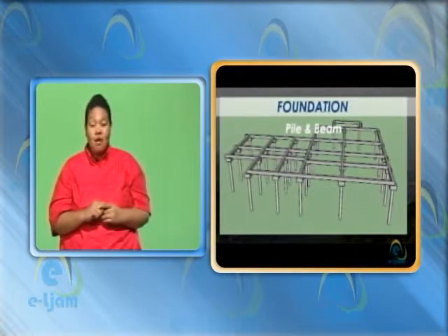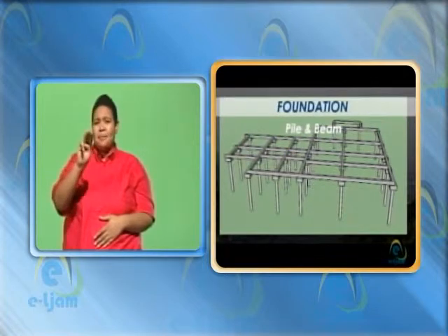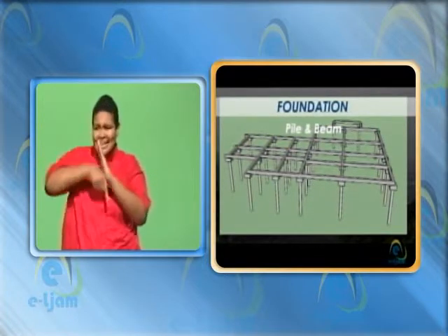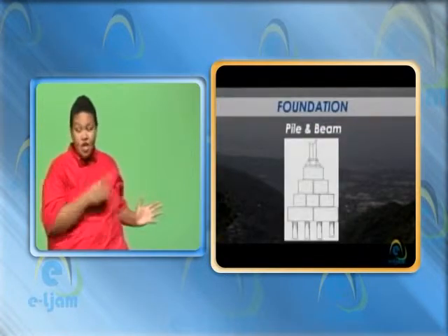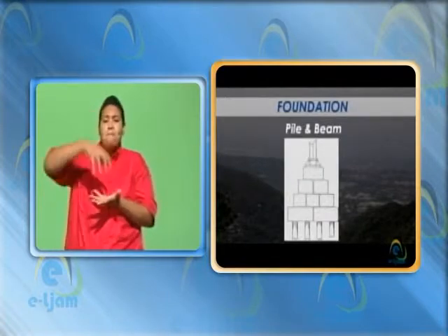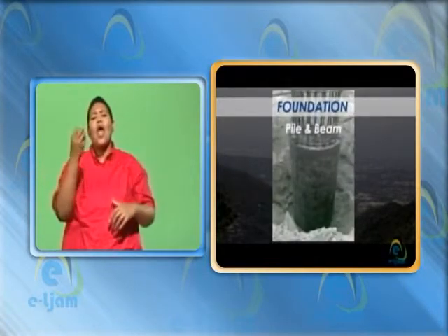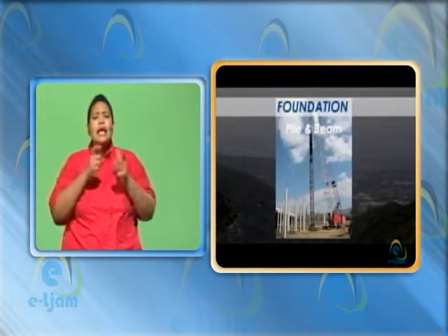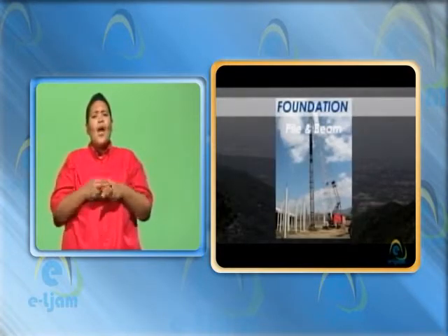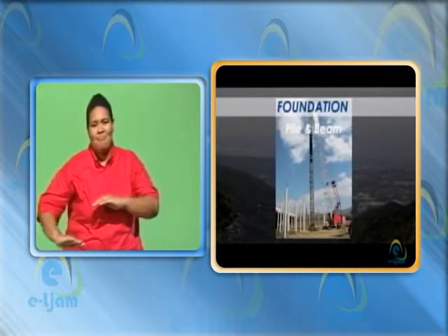4. Pile and beam foundation is an alternative to deep strip foundation. It is required when buildings are erected on clay, marshy, or soft soil. The piles enable the builder to have the weight of the building carried by firmer ground below the poor topsoil.